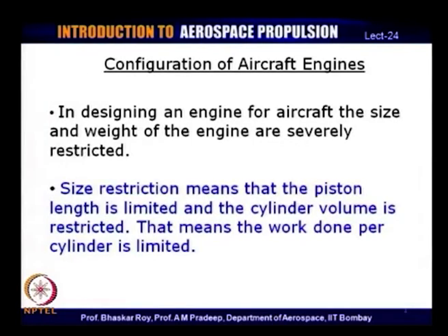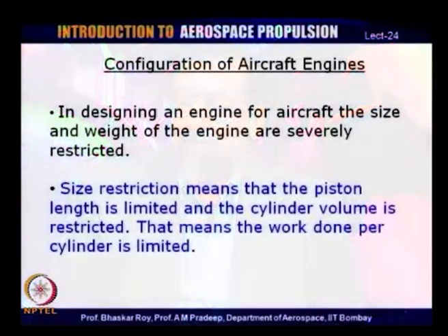This means there is a restriction on the total number of cylinders and the size of each cylinder that can go on an aircraft, because finally, whatever goes on an aircraft has to meet the aircraft shape. The shape of the aircraft is very important to make it airworthy, and as a result there is a restriction on the piston length and cylinder volume that can go on an aircraft.